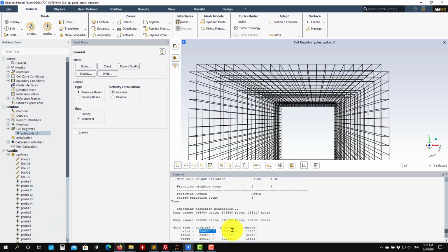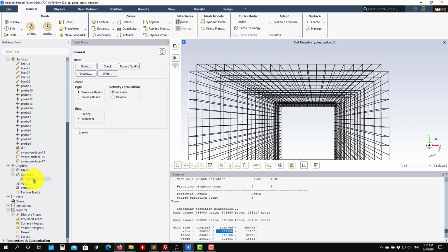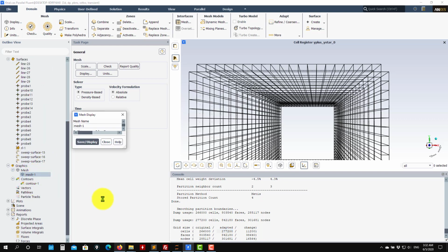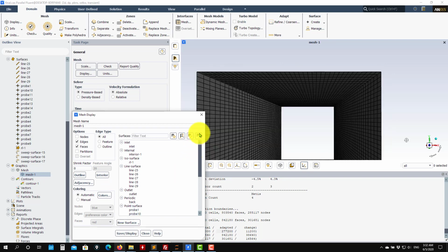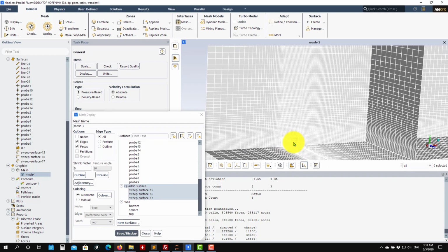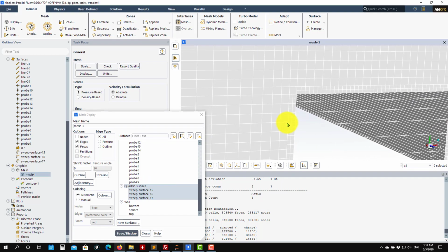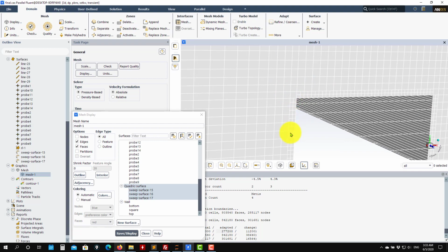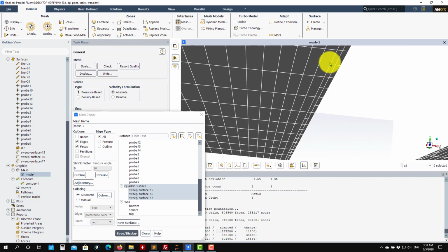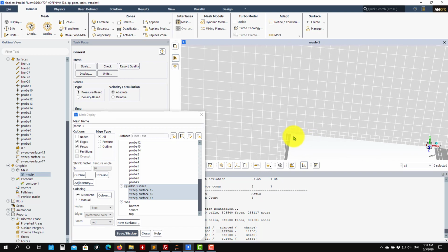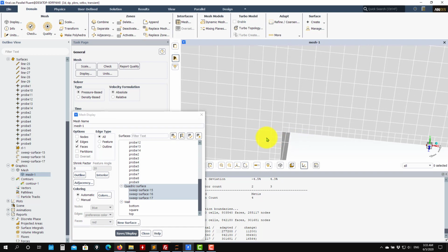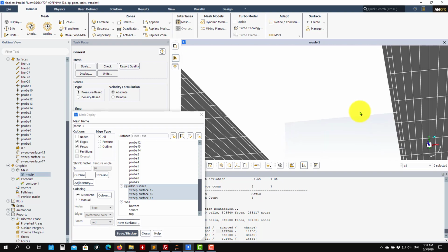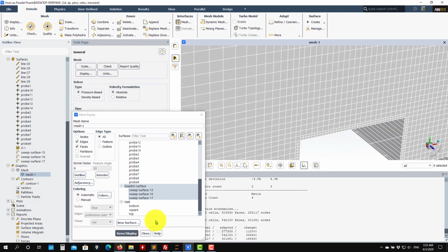So as you go, you select new, refine, and see that it will be automatically refined, just those cells. Okay, so see original, adapted. So if we go back to mesh, in this case, and as you zoom in, see that the cells were split, and even here in this direction. Okay, so it's practical because you need to go back to the mesh, but it's not ideal. You know that probably this refinement will be really easy to do in the mesh utility.